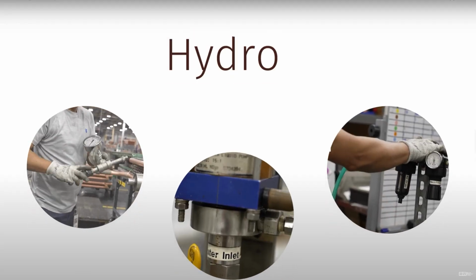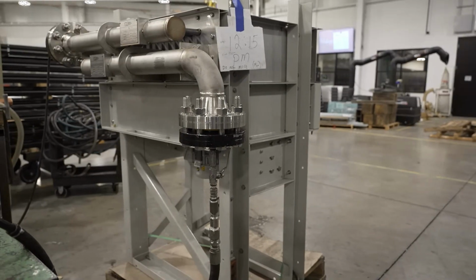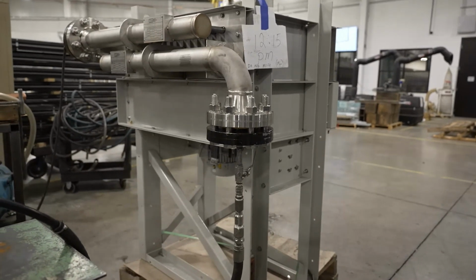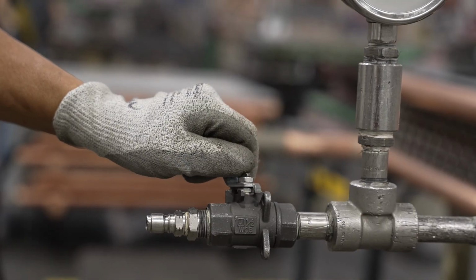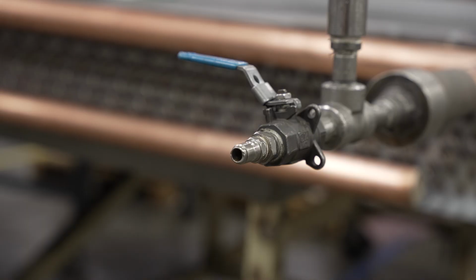The second is hydro testing, which is typically used for high pressure applications. This method involves filling the coil with water and applying pressure. If we see water coming from the coil, there's a leak.